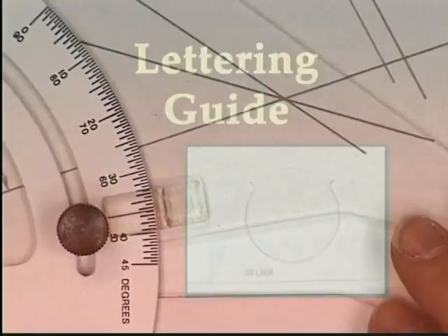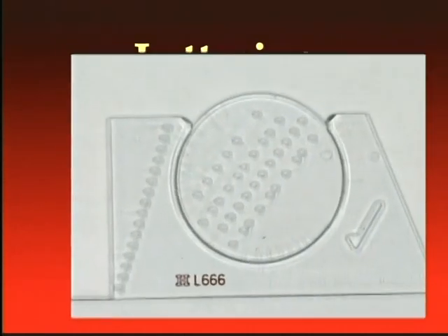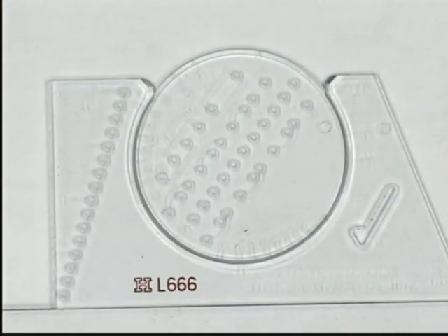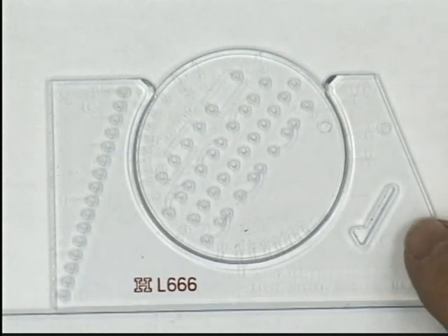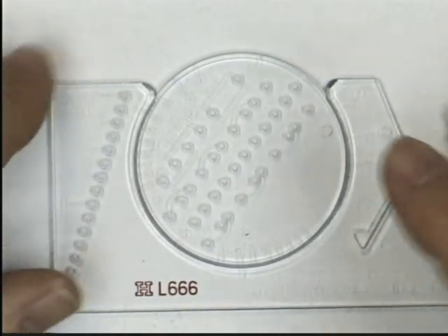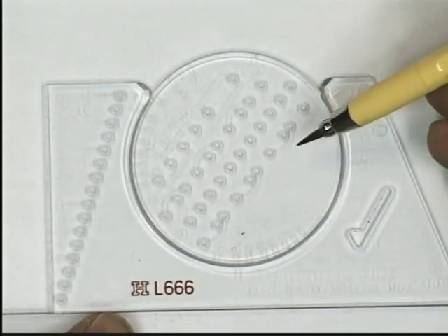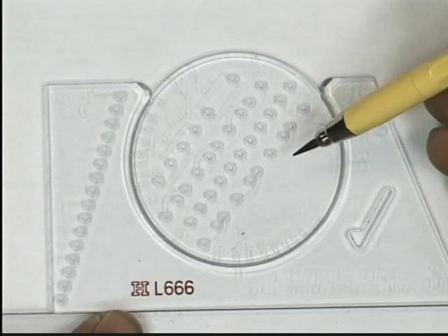Before you get too far into your drawing career, you'll have to start adding words to your drawing. And since the words communicate technical information, the lettering in your words has to be very precise and neat. And you'll want to make guidelines so that your lettering will be of uniform height. And this is one way to do it. This is called an Ames lettering guide, and it has a bunch of little holes in here. So I'm going to have to use my conical point pencil, sharpened pretty sharp, and it has this center circle,